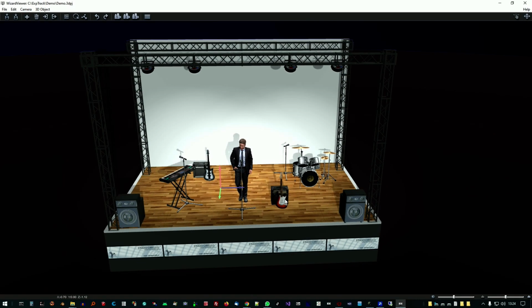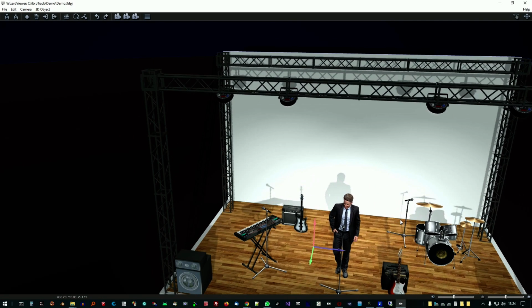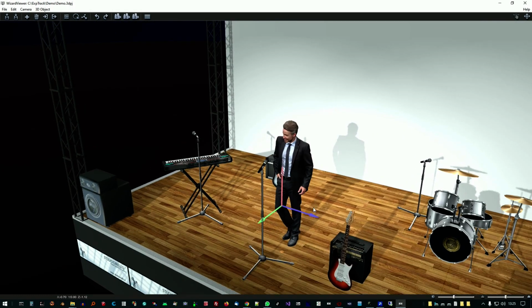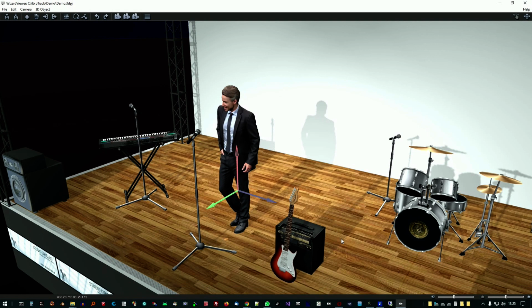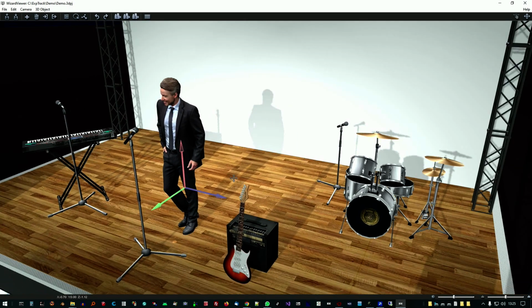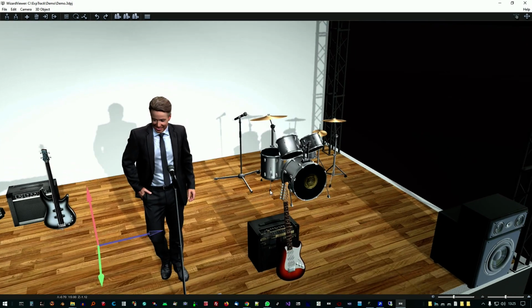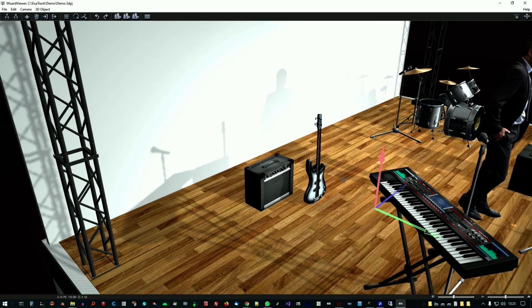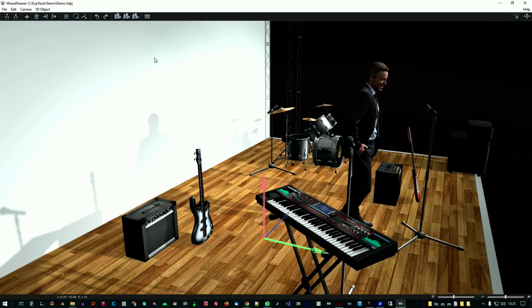In addition to the main views, 3 distinct custom cameras can be stored. We choose a view by moving the mouse in the 3D scene. We store the cameras by pressing the corresponding icon plus the control key on the keyboard. In this way we have assigned the positions that we can recall by selecting the corresponding camera. All movements and modifications are rendered in real time even during the play of the timeline, allowing you to try out the scenes in a simple and intuitive way.